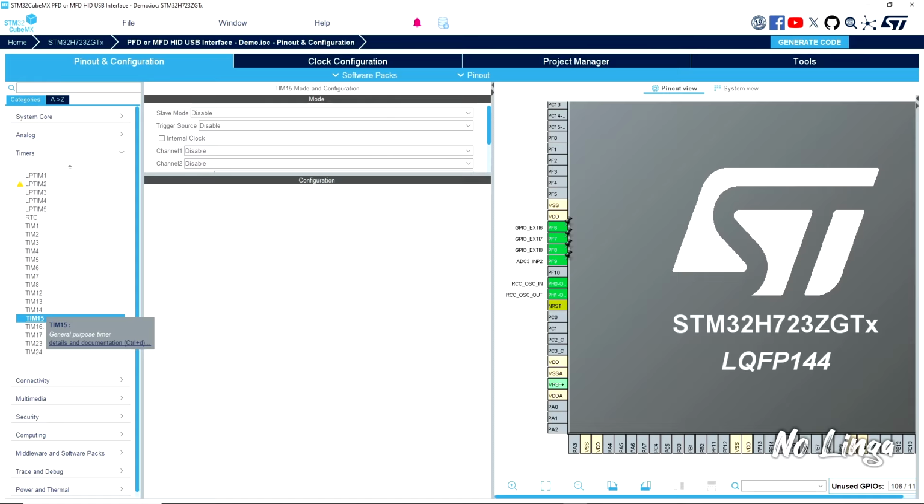Instead of using a while loop to poll, it's best to actually use an update timer. That way you're not tying up resources, and you can send your USB HID signal on a timed event. It can do it every millisecond or 5 milliseconds based on the speed that you want. So let's go do the configurations now.